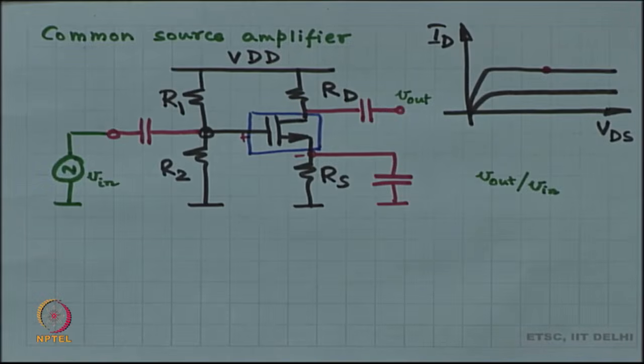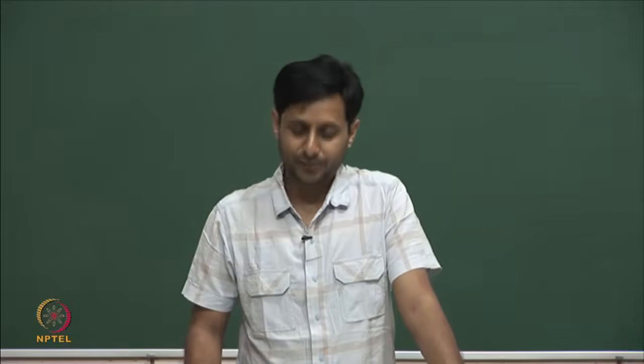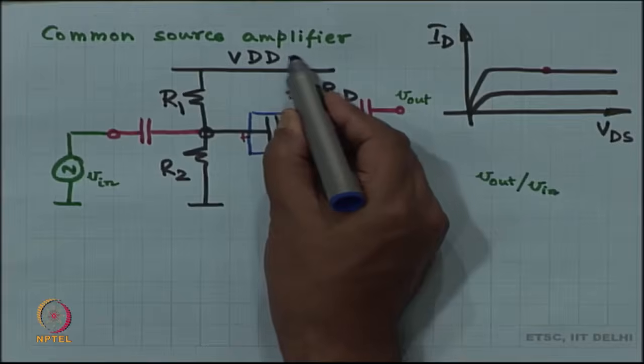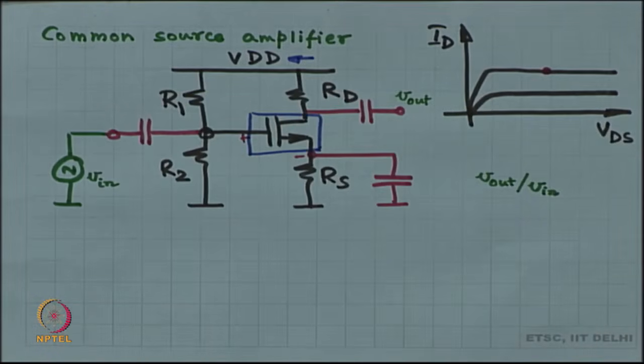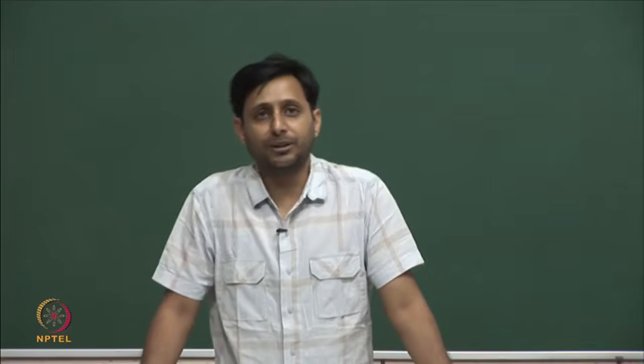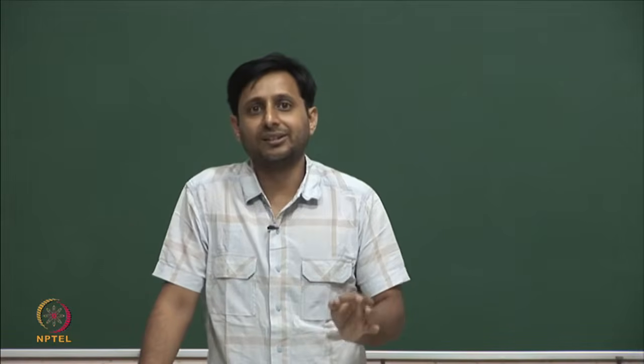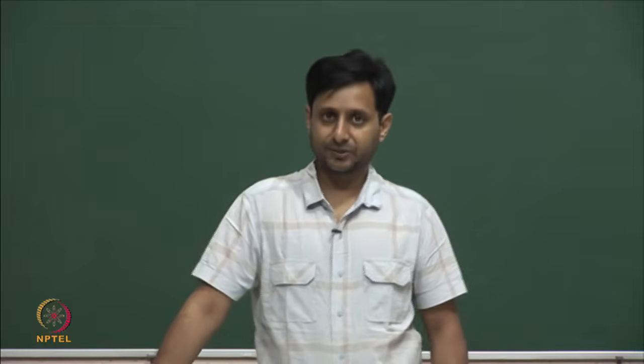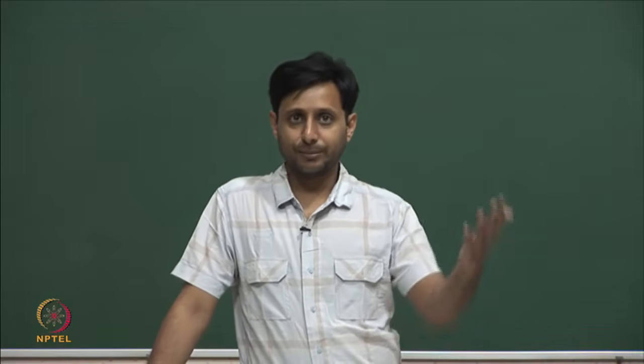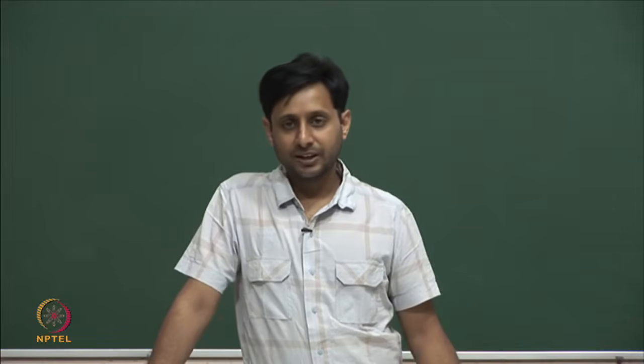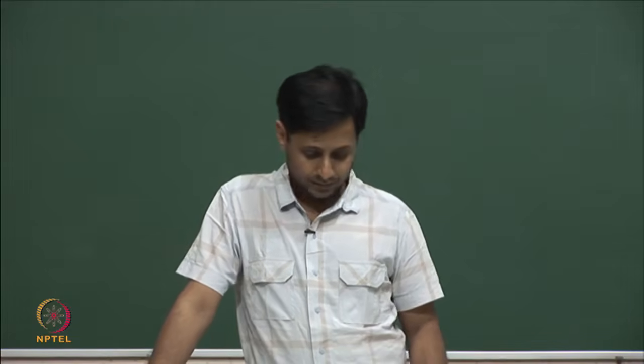And when we are talking about the small signal incremental picture, then power sources like VDD have to be nulled, because these are not changing with time, right. So, the small signal incremental VDD is 0. Okay. So, every node that we are talking about should have their small signal incremental quantities prescribed. So, if it is a current source, it will become open circuit. If it is a voltage source, it becomes a ground. All right.